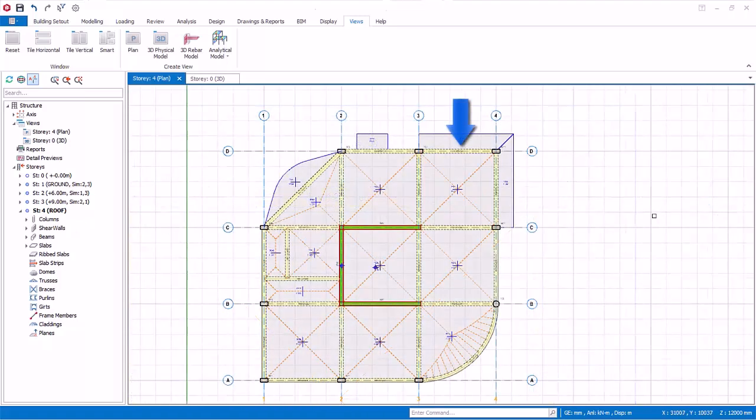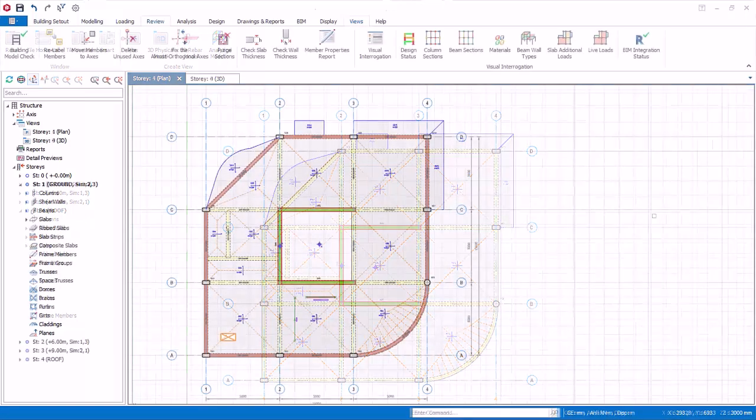For beams, after labeling the last horizontal beam, at the top right, the labeling continues for vertical beam. The first vertical beam label will continue at the bottom left. The label will then increment vertically. Then the labeling will continue along the next vertical axis on the right, until all vertical beams are labeled. The last vertical beam label will be at the top right.